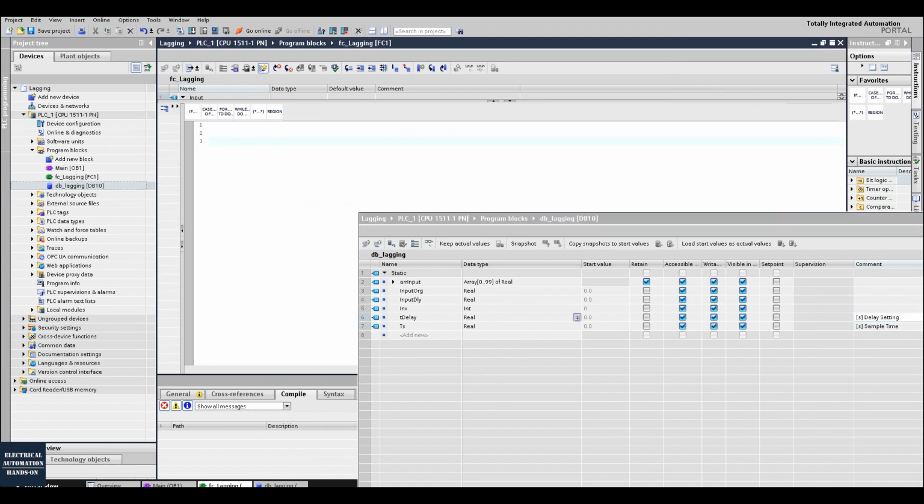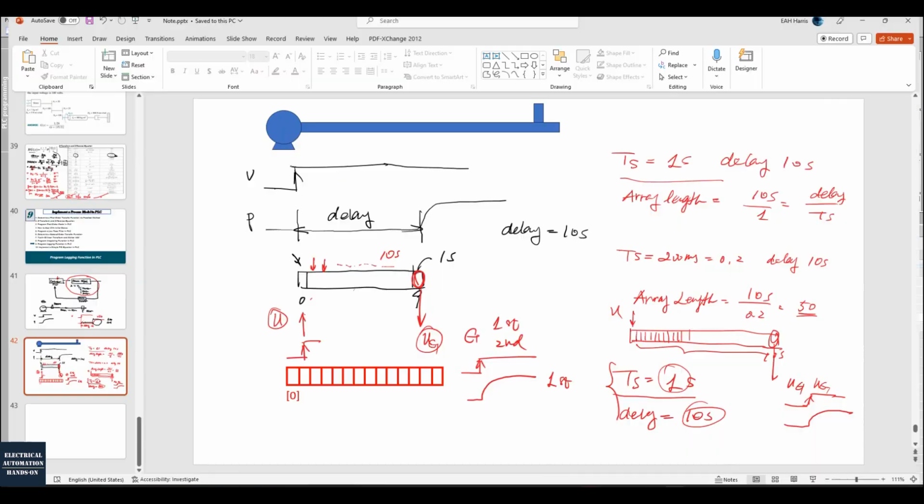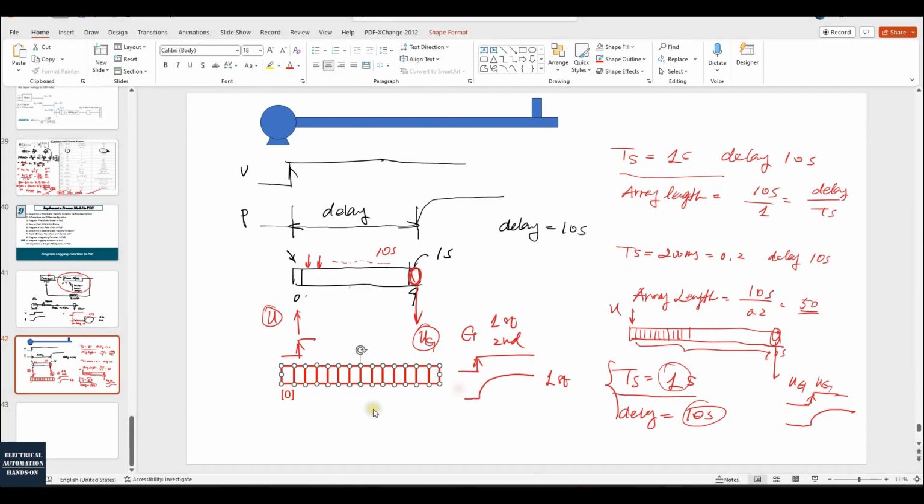So firstly, we will program a very important concept, that's shifting the array. Again, if we go back to this concept, this is the array buffer we have now. Anytime a new data comes in here, the new data always comes in at index 0. Basically, you can understand this: if this goes vertical, this 0 is at the top of this array, or at the very left side of this array. Then before we insert here, every item will shift one item from left to right, or from top to down.